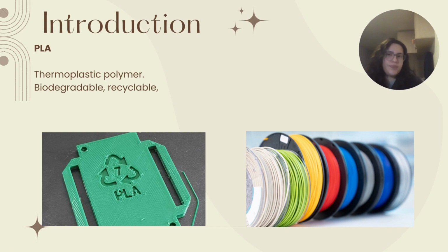But what is PLA? Well, lactic acid or PLA is a thermoplastic polymer obtained mostly from corn or sugarcane, which makes it biodegradable. In addition to the latter, its most notable characteristics are its possibility of being recycled, its high mechanical resistance, its good wear properties, its easy processing, and low toxicity. However, it has some disadvantages of its use, such as very low thermal stability and low impact resistance.